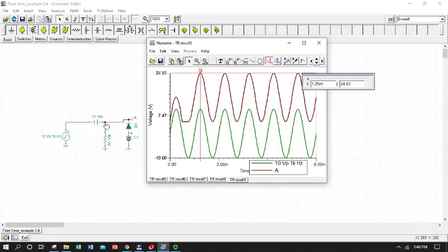So we have 10 volts at the capacitor plus what we're getting from this branch. So we have those adding together at point A, so we'd predict we would have something like 15 and a bit. Excuse me, we'll have the full peak to peak. So we'll end up with 20 and a bit, which is what we see, 24.95. So about 25.